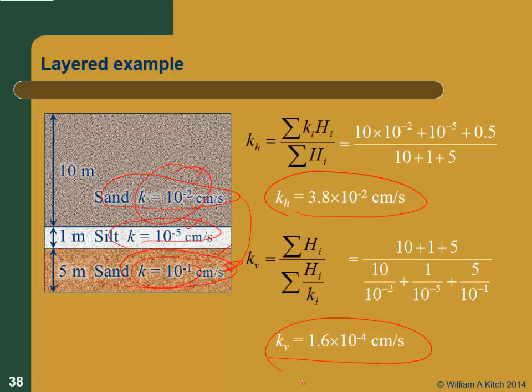Now that's not always true because, for instance, we are uphill of the fault here on campus, and that fault has a big gouge layer in it, and the water table up here is only a few feet deep. If you go about 100 feet in that direction, you get the other side of the fault, where the water table is like 40 or 50 feet deep. Because that's a vertically oriented barrier there, it's actually an underwater dam holding the water up on this side.